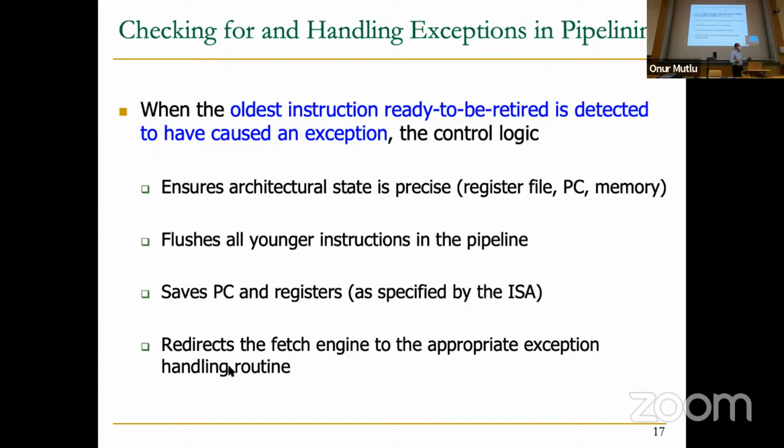For example, with an undefined instruction, you may not be able to restart. If the program tried to execute an undefined instruction, you may not be able to go back to the program unless the programmer knows something. As I said, the programmer can supply these exception handling routines as well. So interrupts are actually exactly the same, except these are interrupt handling routines. You need to change "caused an exception" to something else. Whenever an interrupt comes and whenever you decide to handle it, you still need to do these things because an interrupt is not associated with an instruction. As we said, it's an external event.